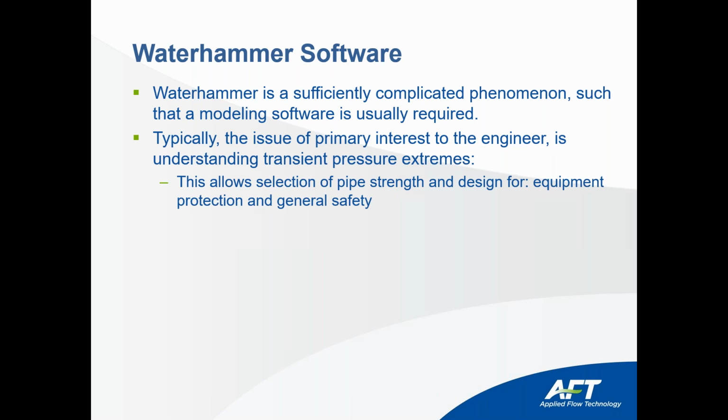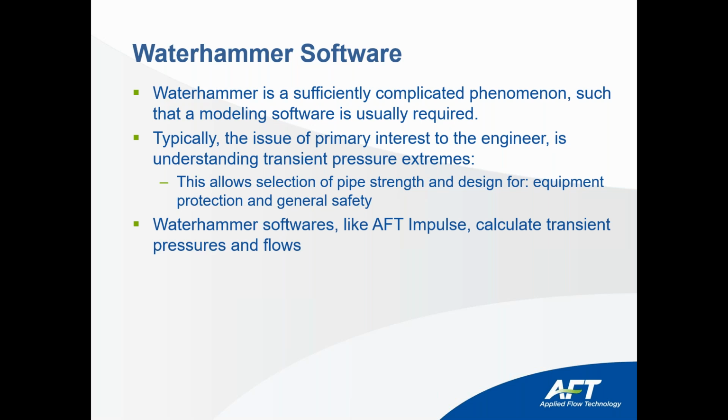This allows the selection of the surge strength and design for equipment protection and general safety in your system. AFT Impulse calculates the transient pressures and flows, and this information is useful to predict the transient imbalance forces that we then use to calculate the stresses in your system.